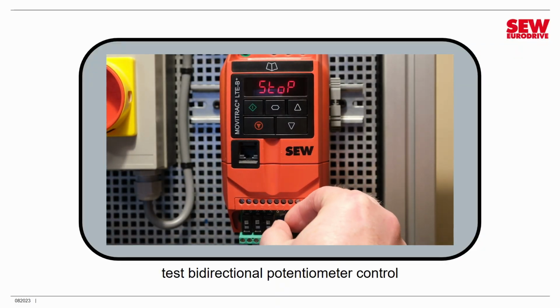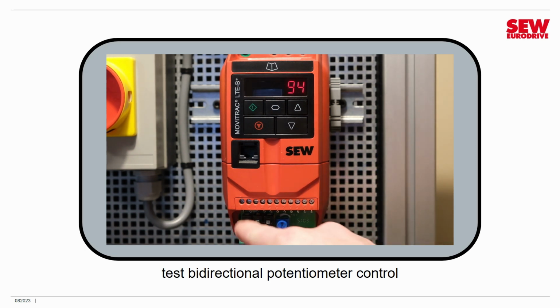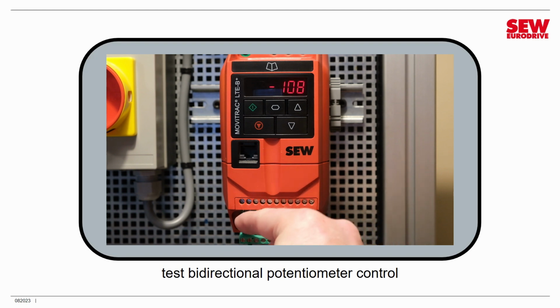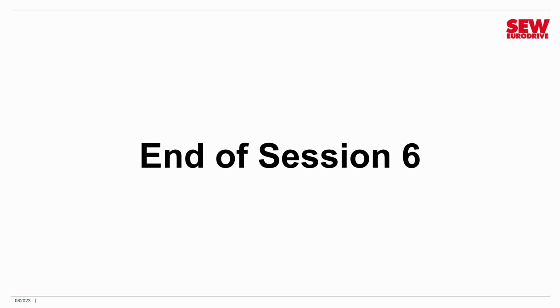All right, I'm going to put the potentiometer in the middle so the drive shouldn't be moving too much, and I'm going to enable it. And you can see there it's just barely turning at about 94 RPM. I turn it clockwise, the drive goes clockwise all the way up to its maximum. If I turn it counterclockwise, it'll bring it to almost a stop when we're near the middle, and then it will go counterclockwise if I keep turning it all the way up to the negative maximum. And if I move it back to the middle, it should come to almost a stop, and now let's switch it off. And we are finally done with terminal control mode.